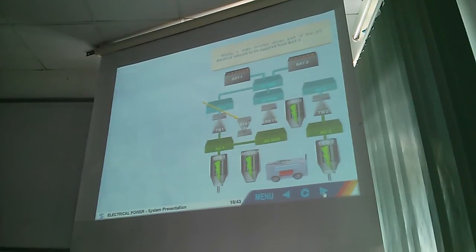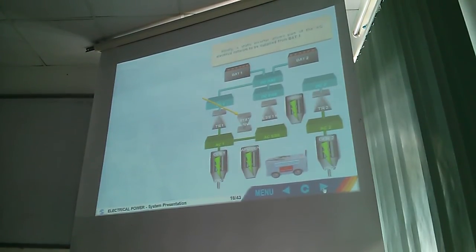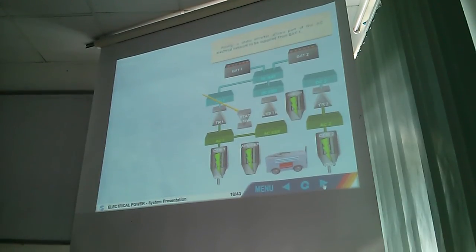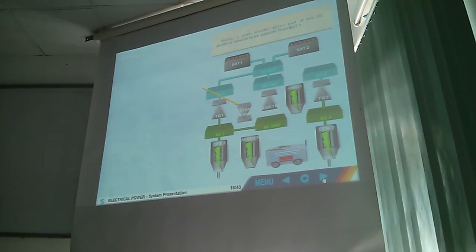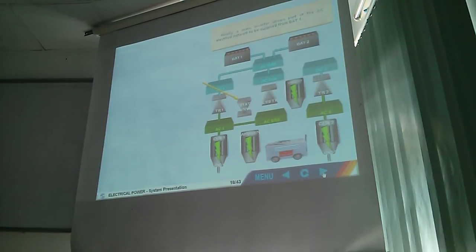If, however, we have no more AC power, everything fails, then we can take power from this bus, put it inside the inverter, and feed some of the AC power. So we can swap everything around in this airplane. So you must know what's happening, because what does Airbus do? It does everything automatically for you. So sometimes when you have a problem, you say, what the heck is going on?